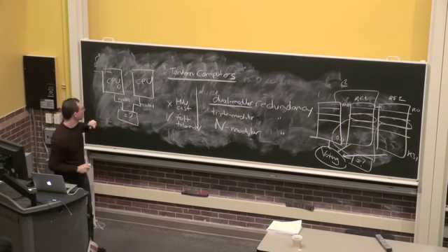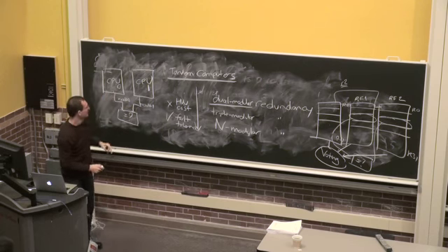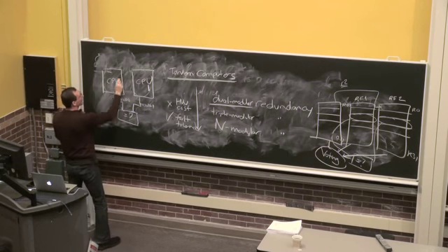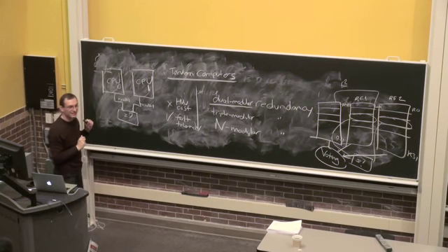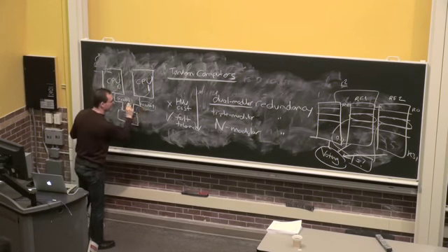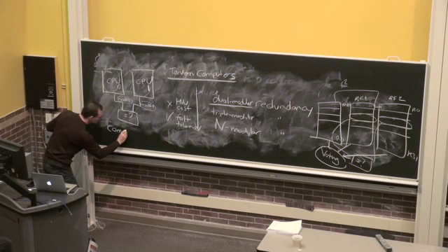This is a common technique employed, and you have a dual modular redundant CPU in this case to tolerate any error, right? So if there's any error that happens in one of them, you can detect it. The only thing you cannot detect is, again, the same error that changes the same bit in both results. And this is called a common mode error, if you will.